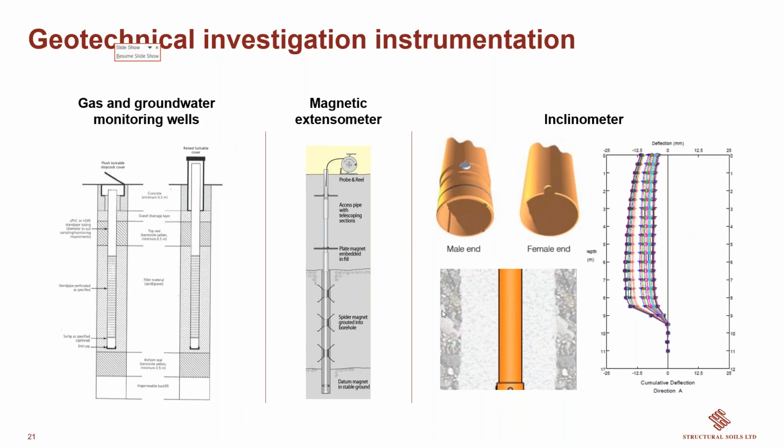On the right-hand side here, we have some inclinometers. This is when we've got a slope that maybe is failing. So when we're using our slope climbing rig, we can drill boreholes, hopefully to find the base of where the failure is, and then we can install the inclinometer. One of the things we need to make sure of is that the depth of the borehole goes beyond the depth of the slip surface, such that when we install it, we can monitor exactly where the slip surface occurs.